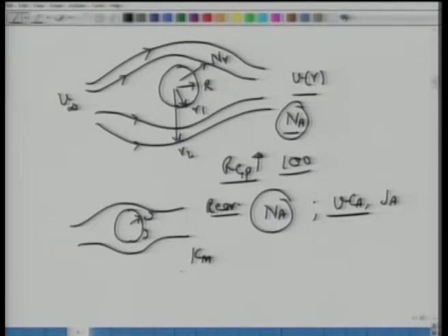and to say that we have the flux now, which we can write as diffusion flux NA as mass transfer coefficient into some concentration difference, where del C is the concentration difference between Cs at the surface and C infinity. Okay, so we are trying to make a case here. What is the motivation of mass transfer coefficients? Why do we have to define this quantity, and where can we get away without defining this mass transfer coefficient?